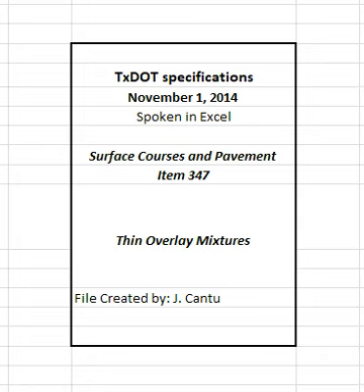The thickness determined is based on the rate of 110 to 115 pounds/square yard for each inch of pavement unless otherwise shown on the plans. Table 9. Compacted lift thickness. See table in specifications. Compacted target lift thickness will be specified on the plans.